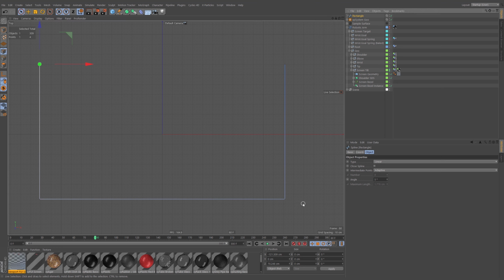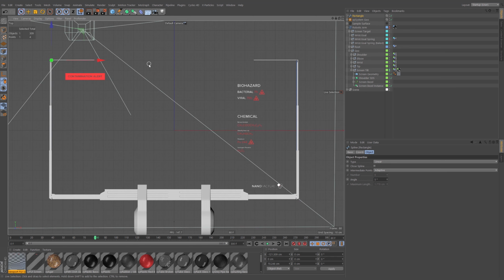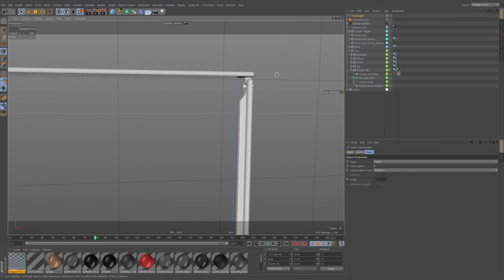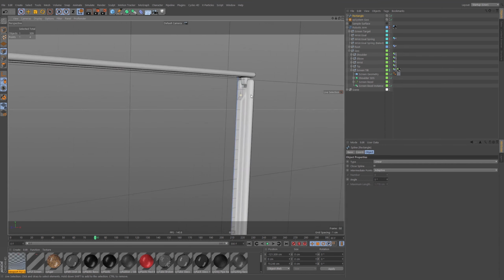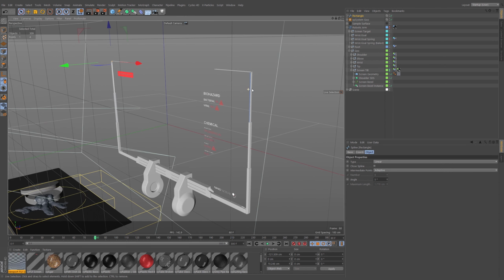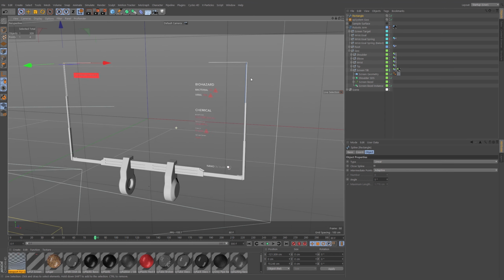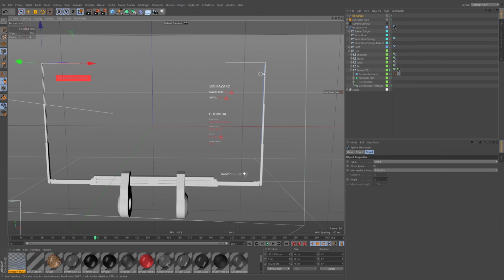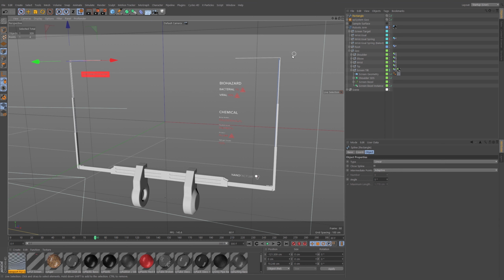Now the next thing is we need to make sure it's positioned in the Z axis, which I think, because it's 0 to the screen, will be perfect, but we'll double check that. And also we need to work out the subdivisions. So let's unsolo that. So solo off. And then let's go to our main view, which is F1. Let's zoom in over here. You can see it's not quite 0, so we might want to push it a bit further along, but that's not a problem at the moment. Just as long as it's aligned, that's the main thing. You can model this in a separate scene, you could do whatever you like. Sometimes I do that, but in this case, it's quite easy to just manipulate it in situ.